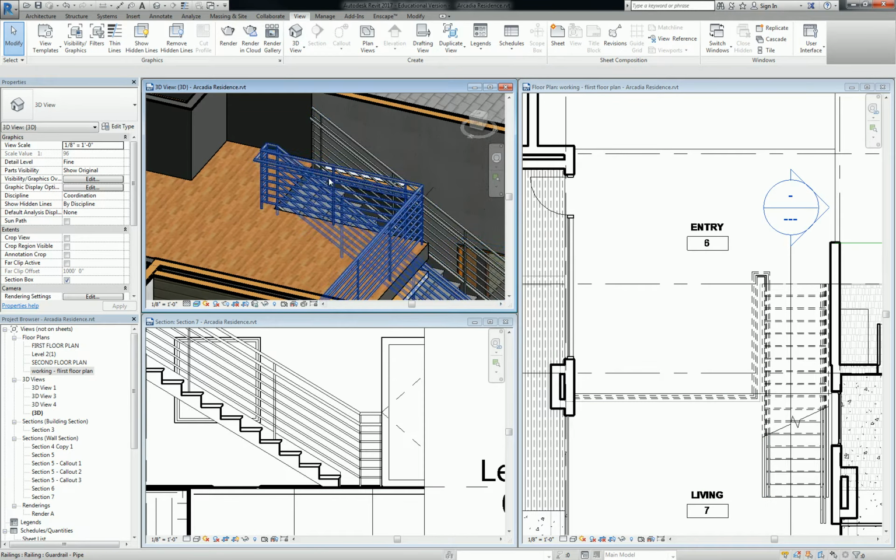When you get to the bottom, that 11-inch extension at the bottom, that's what it basically resets the distance so that at the top of the rail to the floor is 3 feet again. Does that make sense? And then at the top, it does the same thing. But you don't need the extension because you're already 36 inches from here to the top of the handrail, and you just need to go horizontal now.